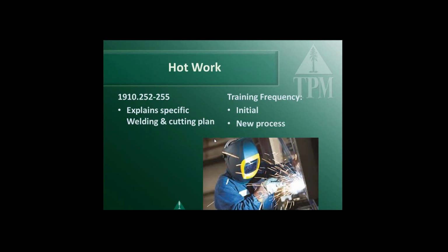Hot work. So one of the big ignition sources, say for the combustible dust too, but with hot work, you want to look at initial training, and if you add a new process. And a lot of times, what are you welding? You have to identify what you're welding. If anything is stainless steel, you probably have chrome in it, and then you better call me because I can help you with that, because the inspectors see stainless steel, they'll think chrome, and then they'll dig in. So you have to be very clear with your welders, the people doing the welding. They need to understand not only the fire hazards and dealing with hot stuff and all that kind of stuff, but also what are the things they're welding.